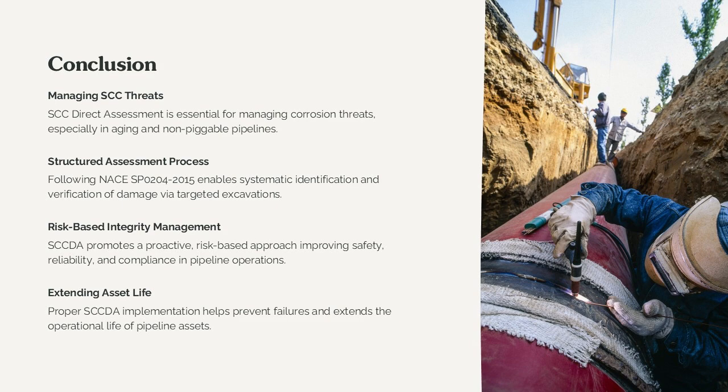Stress corrosion cracking direct assessment is a critical methodology for managing SCC threats in pipeline systems, particularly for aging infrastructure and non-piggable lines. By following the structured process defined in NACE SP 0204-2015, operators can systematically identify susceptible segments, verify damage through targeted excavations, and implement effective mitigation measures.